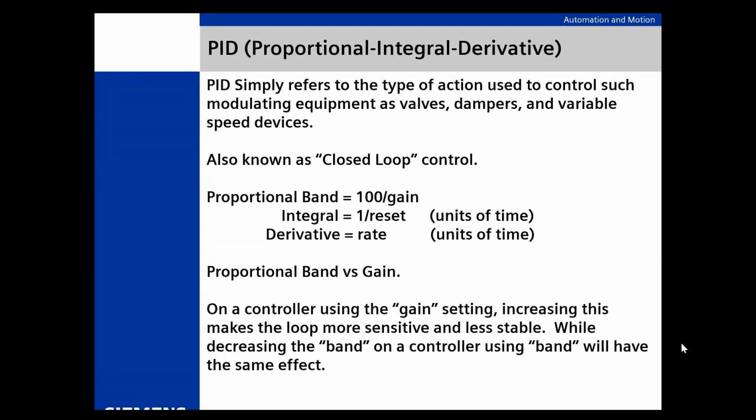So you're going to hear more proportional band. And that's okay. Don't worry if, say, this guy from Siemens said something about gain. Well, you're probably never going to hear that. I haven't heard it in years and years and years, unless I'm talking to somebody my age. So don't worry about it. Again, if it pops up, you know what it is. It's just the inverse of band. Most people talk about band these days. In fact, everybody does. All right.